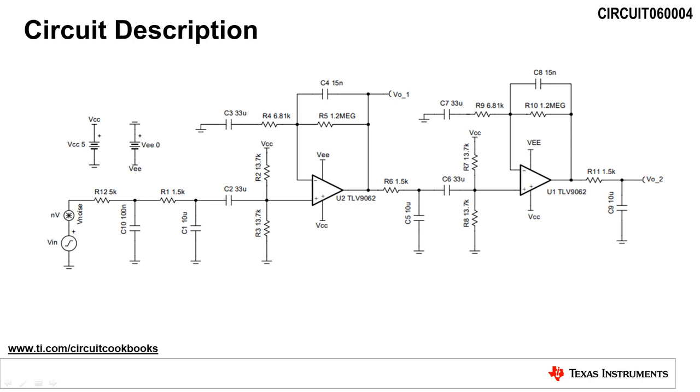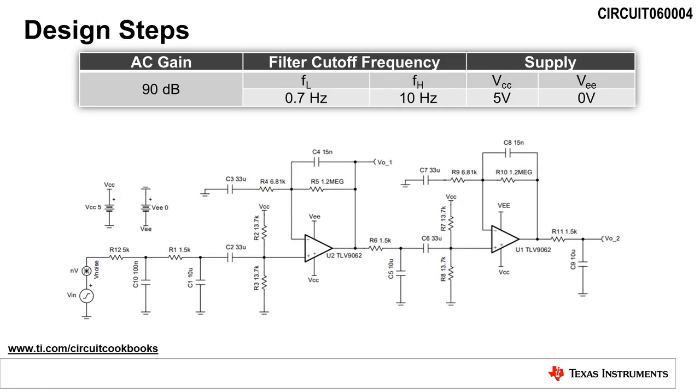Multiple low-pass and high-pass filters are used in the design to reduce the total noise at the output of the circuit, which allows for motion detection at long ranges and reduces false triggers. This circuit can be followed by a window comparator circuit to create a digital output.